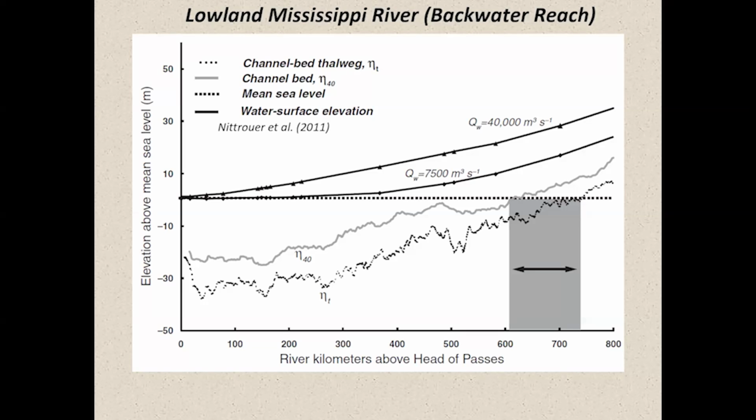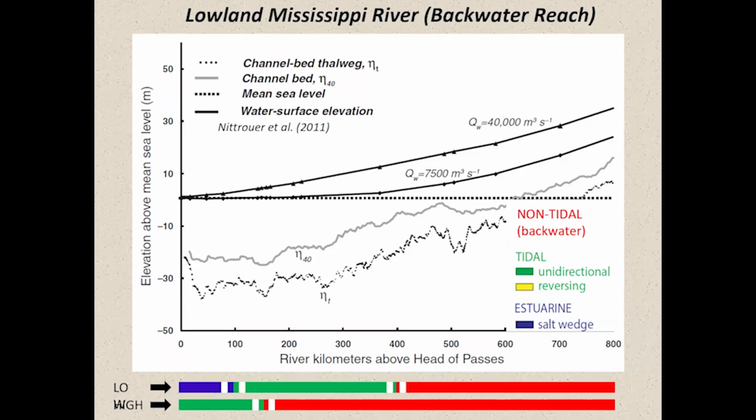sediment through the system. Another thing that's key in this area, that 730 kilometer point, you notice is the point where the channel bed thalweg rises to above sea level, right? So again, that gives you a sense of why we're in this backwater reach. So this is the part of the system I'm going to concentrate on.